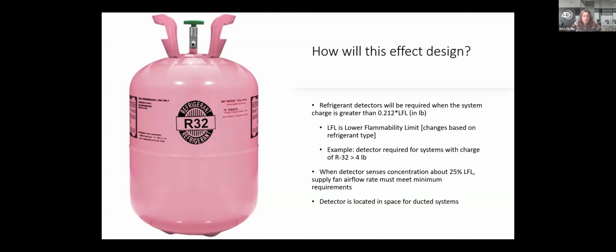Sounds good. All right, for condensing unit replacement of an existing system, existing lines could not be used. They're within concealed walls. So this is tough, David. Systems are required to use the refrigerant that they are designed for. You cannot replace an A1 refrigerant with an A2L and maintain the same equipment.